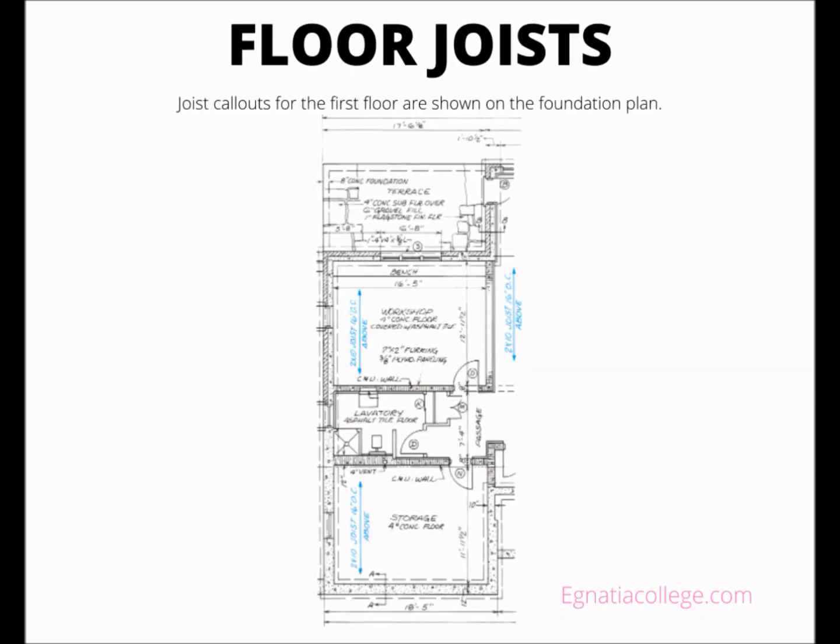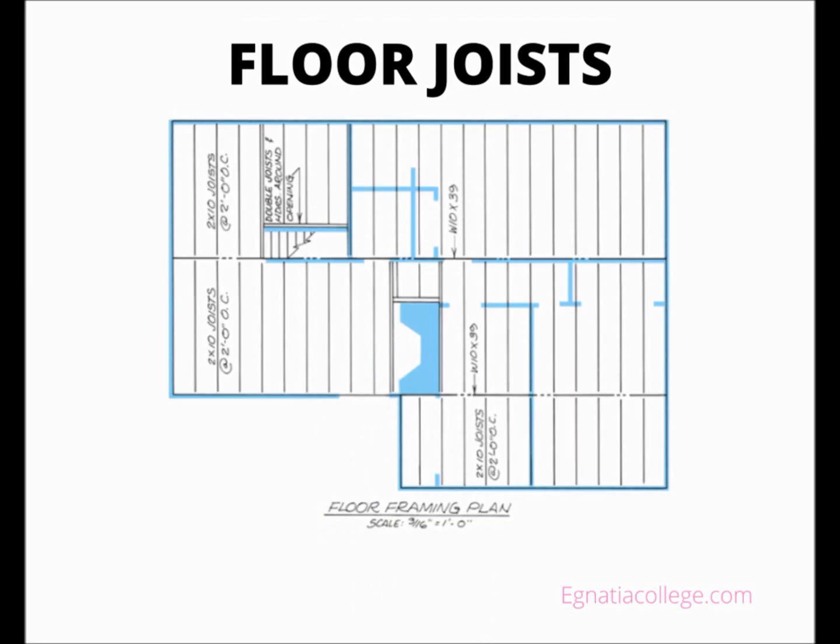as the I-joists. Notes on the floor plans indicate the size, direction, and spacing of the joists in the floor above. For example, notes on the foundation plan give the information for the first floor framing. When the arrangement of framing members is complicated, a framing plan may be included. On most framing plans, each member is represented by a single line.